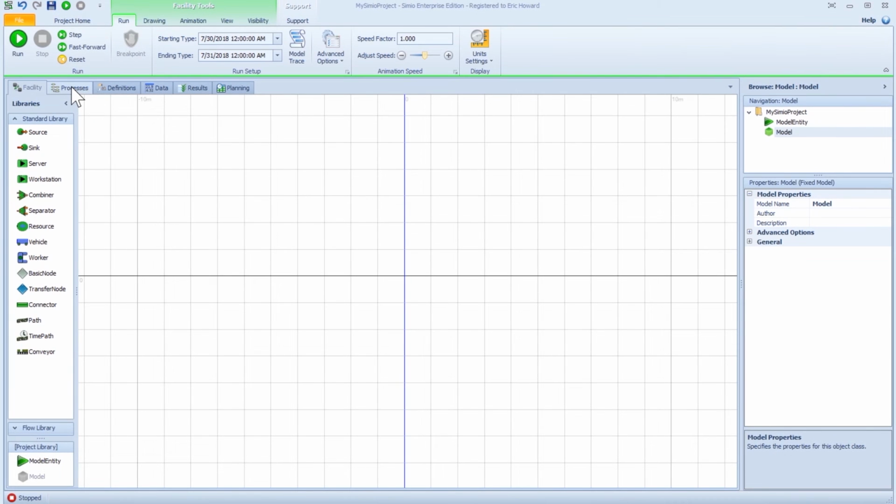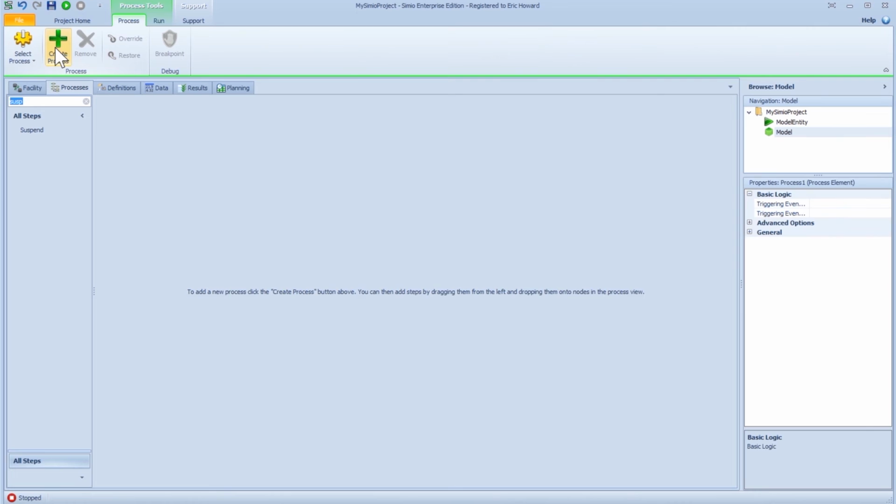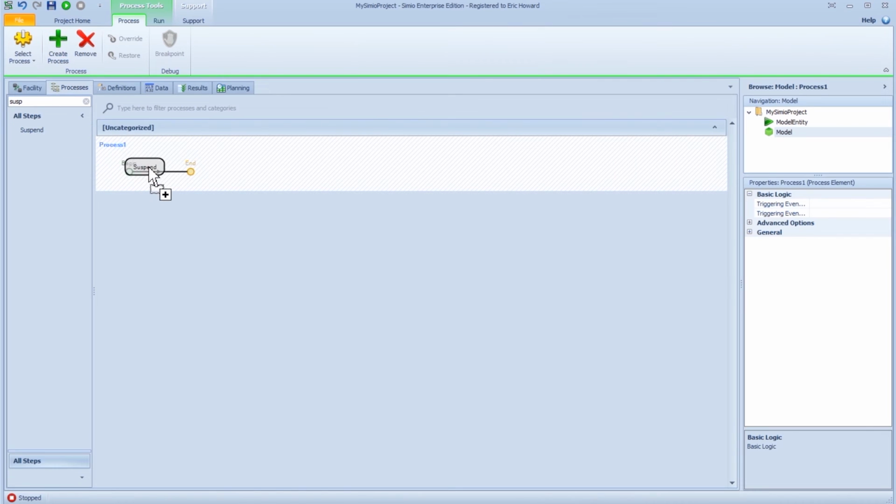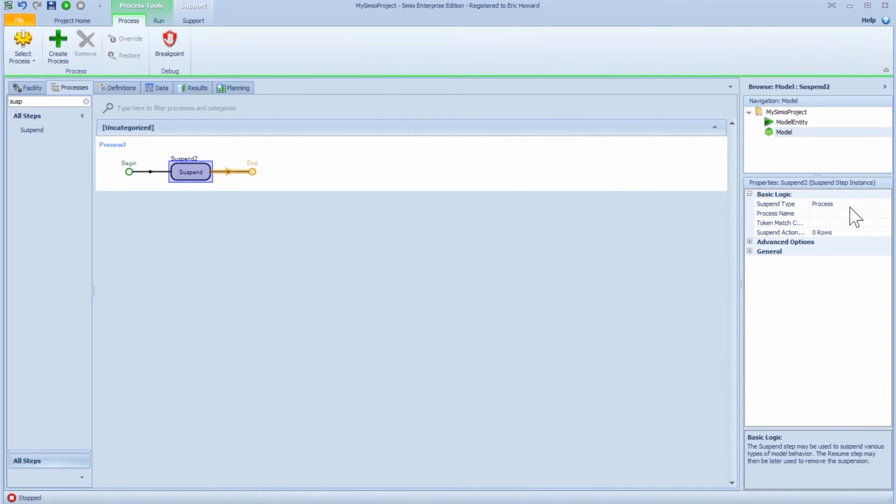Standard Library Combiner. New Suspend Batching when down property. There is a new property for the combiner object within the standard library, within the batching logic section of properties. When Suspend Batching when down is set to true, the actual collection of batches will be stopped if the combiner has failed or changes capacity to 0 from a work schedule shift change.